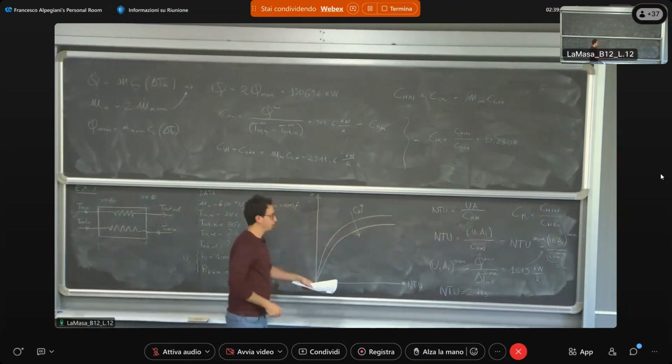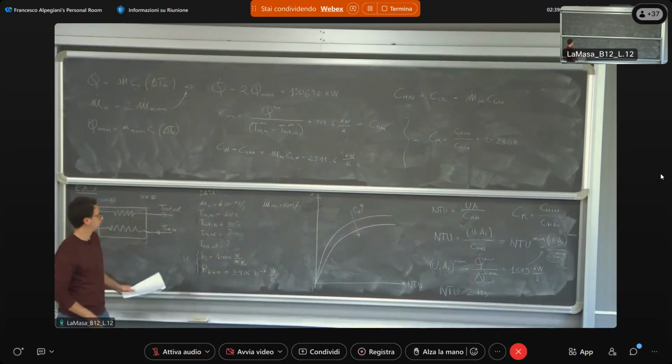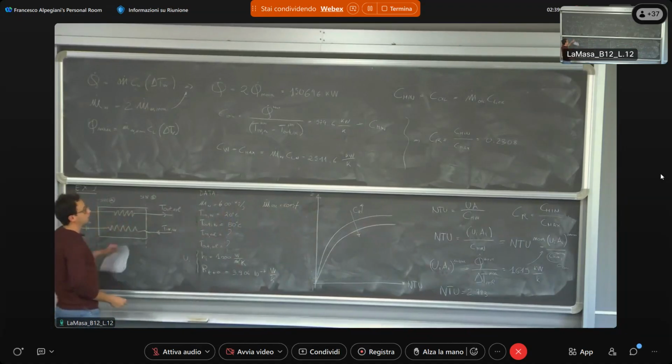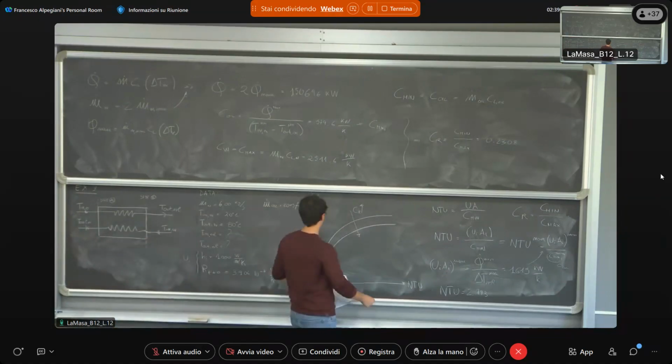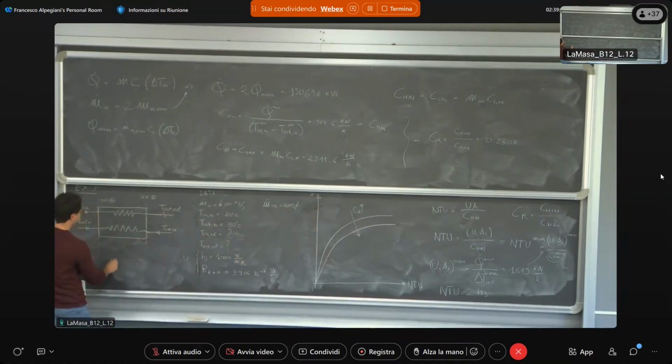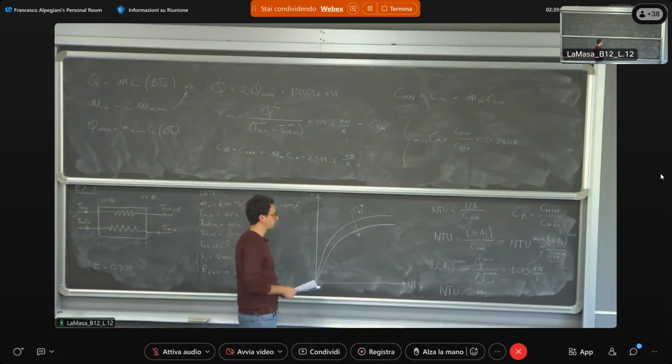So then, exploiting the formula, which is given in the text, you can derive the new effectiveness of the heat exchanger. Epsilon in off design condition is equal to 0.908, and you can notice that with respect to the value that we have evaluated before it is greater.